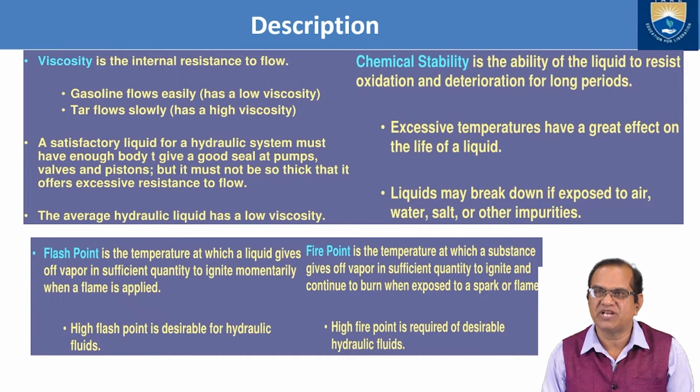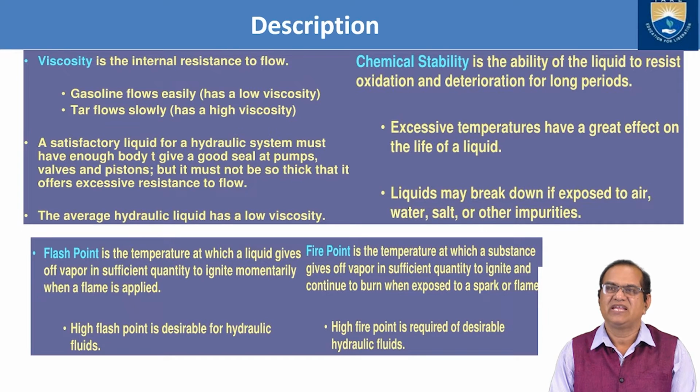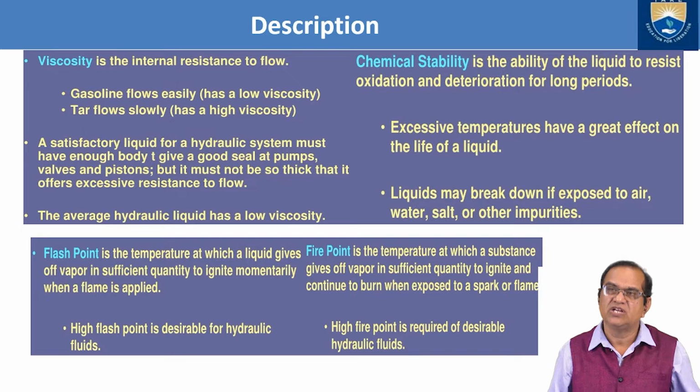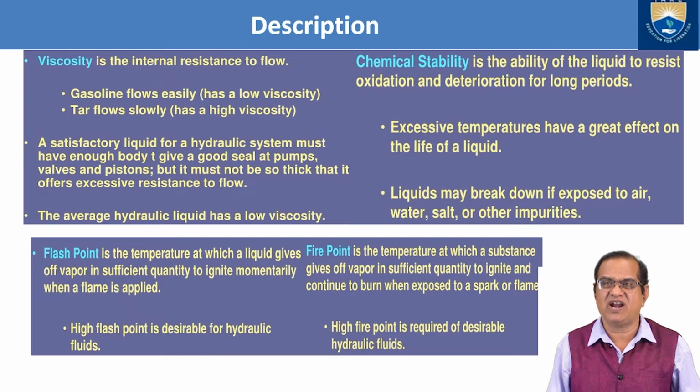Fire point is the temperature at which a substance gives off vapor in sufficient quantity to ignite and continue to burn when exposed to a spark or a flame. So the fire point also should be very high. A high fire point is required of desirable hydraulic fluids.